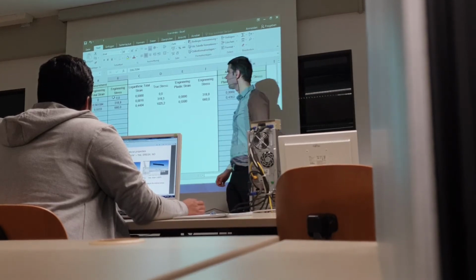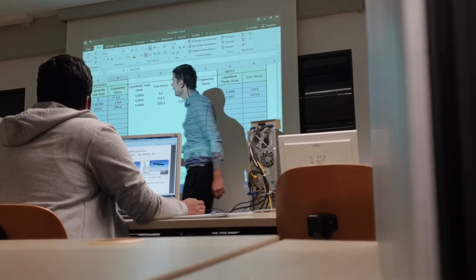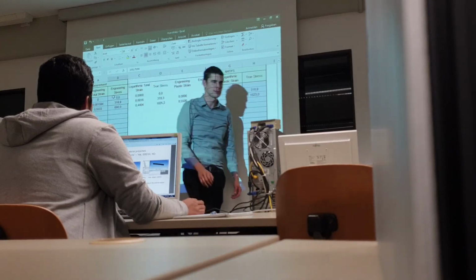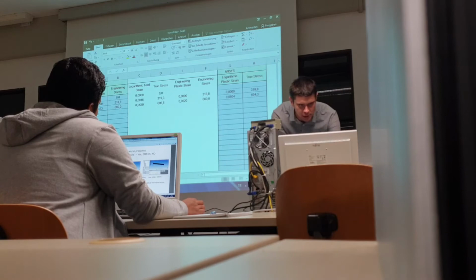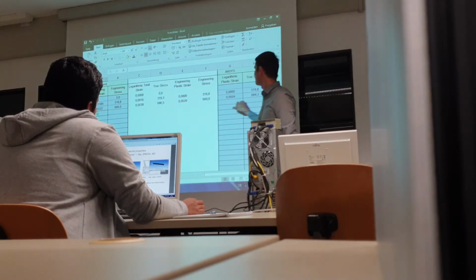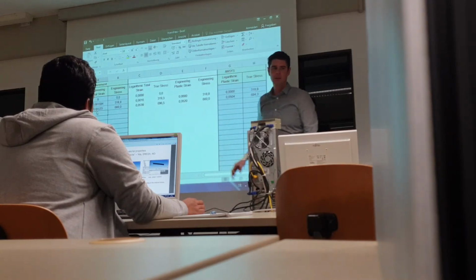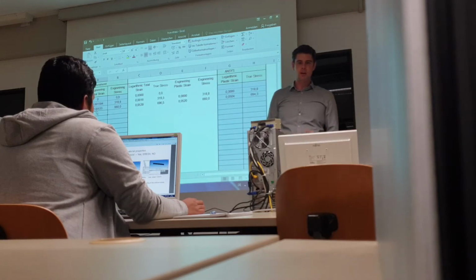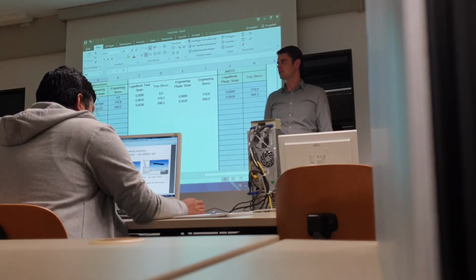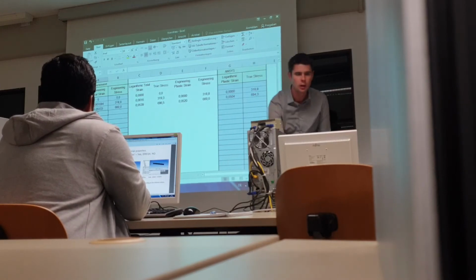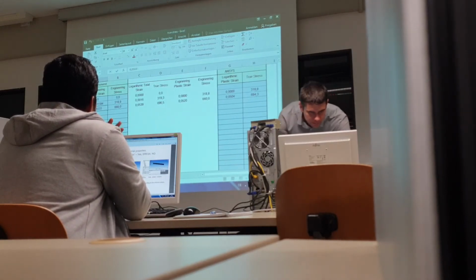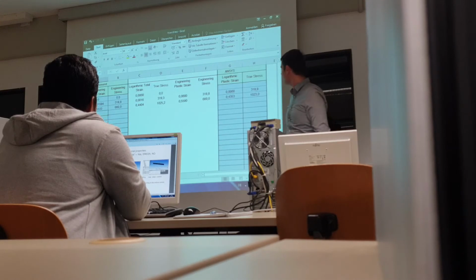It's easy to show the difference. Normally I do not have such big deformations. For example, if I have 0.05 deformation, then it's not such a big difference between the two points. And then many people say, okay, I use this. But normally you always have to use true stress. So it means I have to define this line in ANSYS.